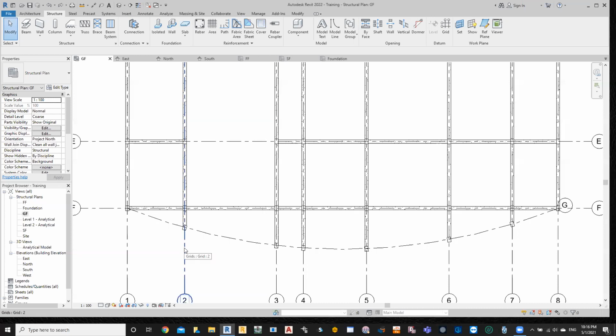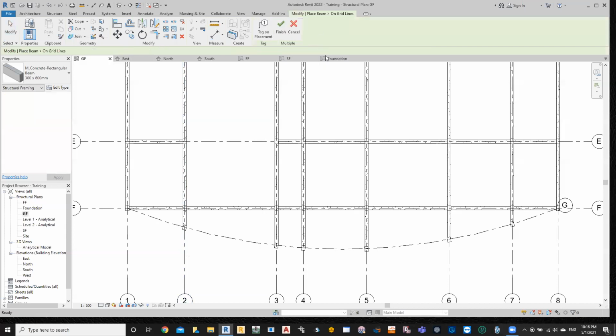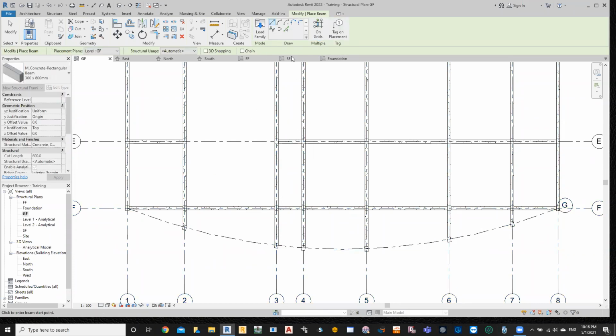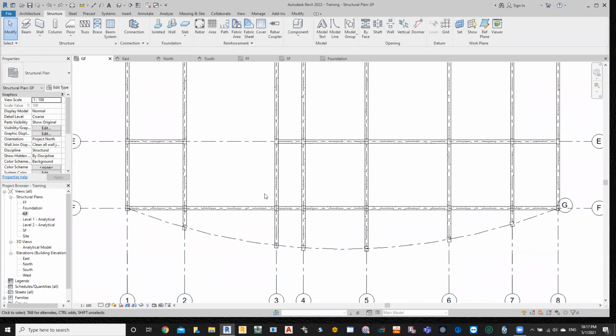Once again, you have two types. I can go for the beam, I can go for the grid, and I'm going to highlight here. You will see now that these particular beams are actually not purely curved. These are actually inclined elements connected together. Can you see? It's not a perfect curve. Are you able to see? Yes. Okay. Now I want to draw a perfect curve.